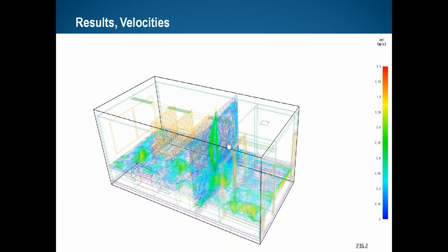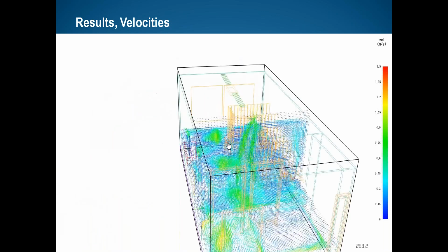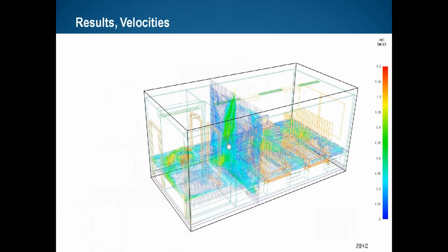For example, if you have 3 million grid cells and you want to see the results every 3 seconds for example 3,000 points around the patient bed, you can bring it in an Excel sheet, and after you take it in the Excel sheet, you can calculate the draft temperature and air diffusion performance index, and calculate all the numerical values. Compare this with your results.